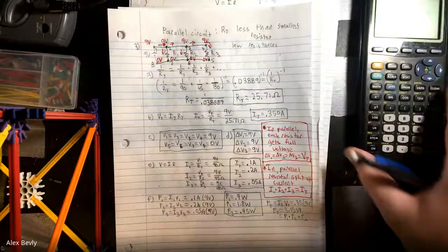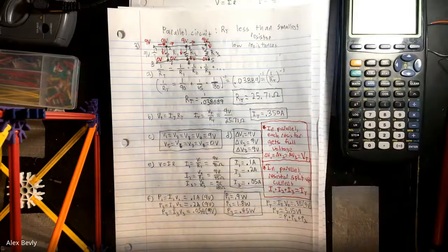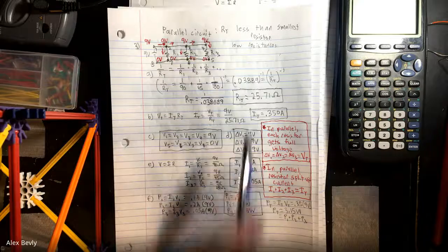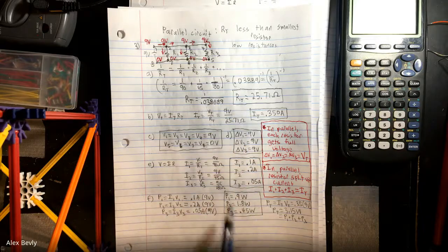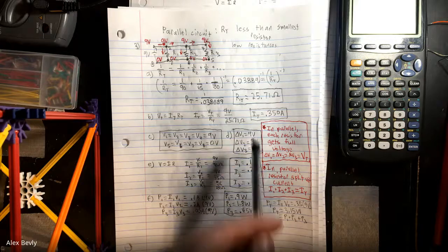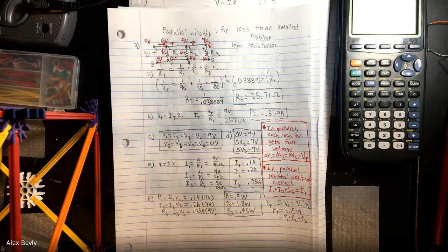That is way more power than series, yes. So that is an advantage. One advantage of parallel is we get smaller resistances, so we get bigger currents. Those bigger currents allow us to get bigger powers, but that can also be a disadvantage, right? A lot of that energy is lost to heat. If you get too much current and too much power, you actually start getting into risks of starting fires and burning things down or overheating components.